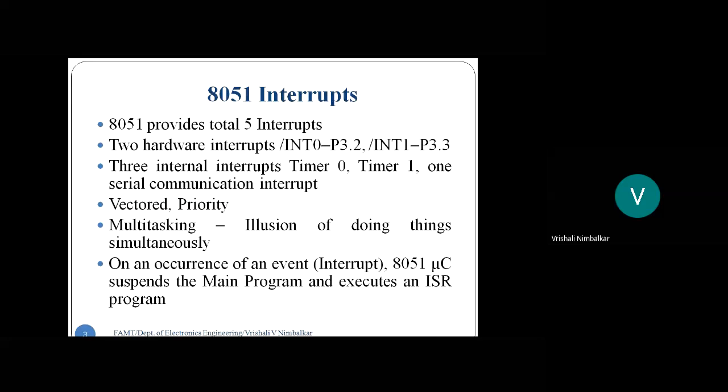The INTR interrupt was non-vectored, if I remember correctly. Non-vectored means that when an interrupt arrives, the microprocessor does not understand on its own where to go. The programmer has to write a program to tell it where to jump.